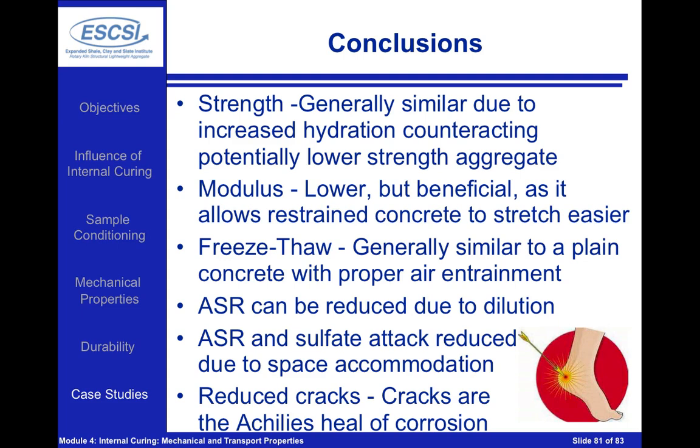Freeze-thaw resistance, we generally see a similar behavior to plain concretes, provided we have proper air entrainment. And remember, the self-desiccation is going to pull water out of the lightweight aggregate. So after a relatively short period of time in a low water to cement ratio concrete, we're going to have pulled the water out of the lightweight aggregate to cure our concrete, and we're not going to have a problem with the water remaining in the lightweight aggregate. So in general, internally cured concrete is going to behave very similar to plain concrete, provided both cases have proper